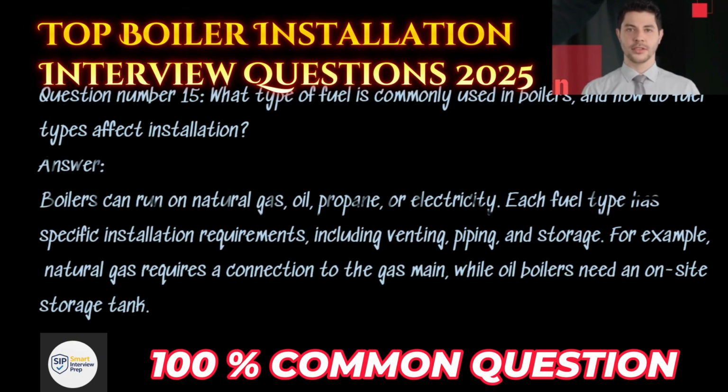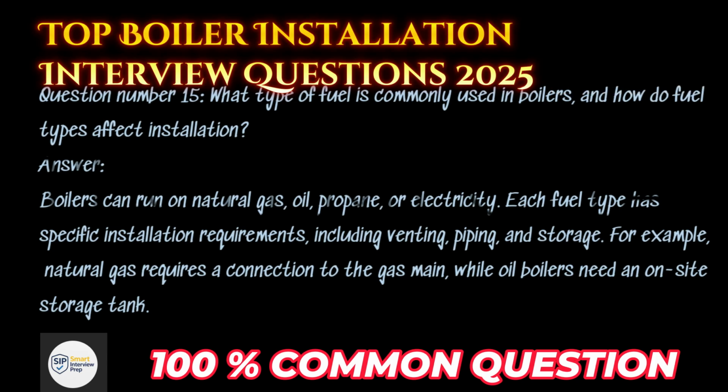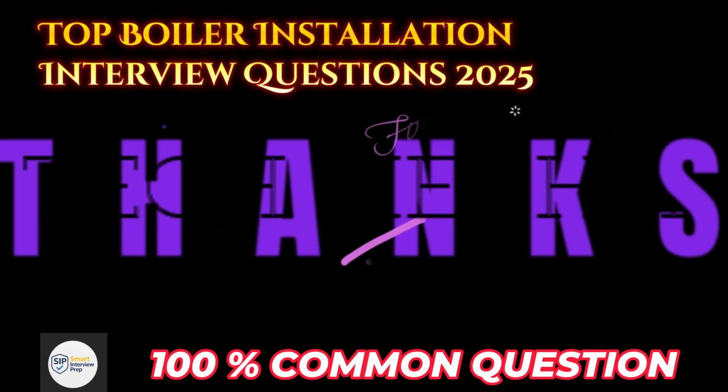Question number 15. What type of fuel is commonly used in boilers, and how do fuel types affect installation? Answer. Boilers can run on natural gas, oil, propane, or electricity. Each fuel type has specific installation requirements, including venting, piping, and storage. For example, natural gas requires a connection to the gas main, while oil boilers need an on-site storage tank.